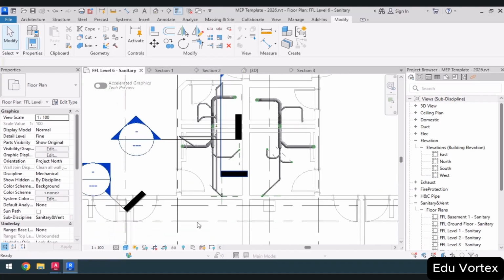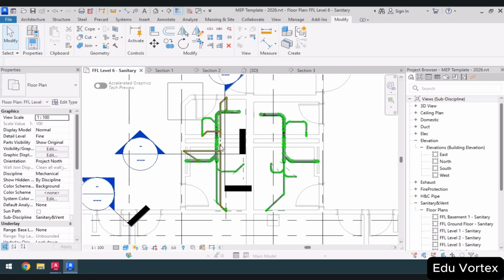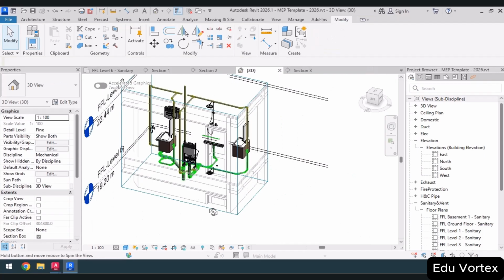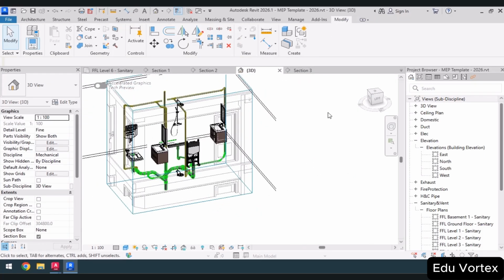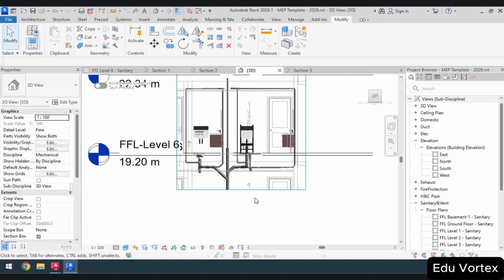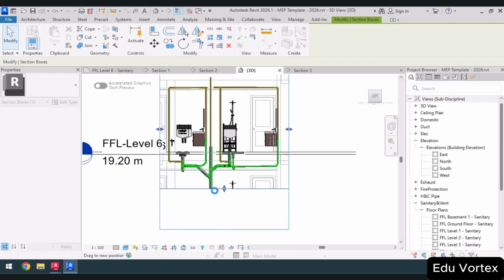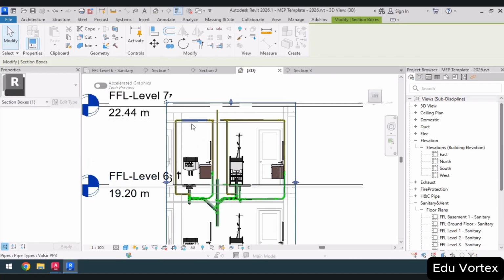Now let's take a look at this piece in 3D. I will select everything using the selection box. Notice that all the wastewater pipes for this floor, especially in level 6, connect to the ceiling of the lower floor, and their vents run up into their own ceiling. This means that in any service area, either eastern or western, all sinks must have their vents moving upwards. So now the placement for these sinks is always clear. I cannot bring them down. Those sinks always go up.